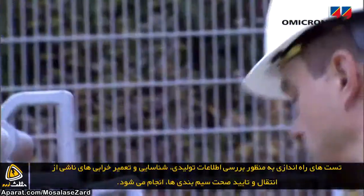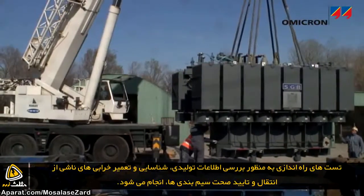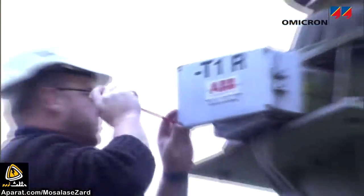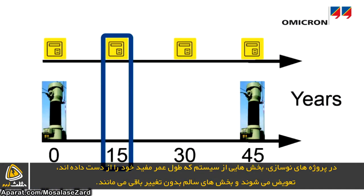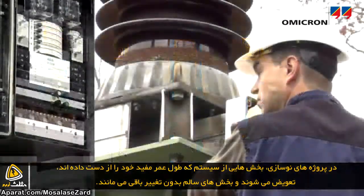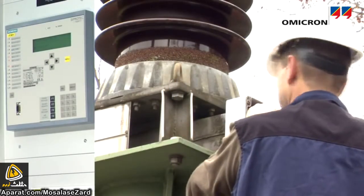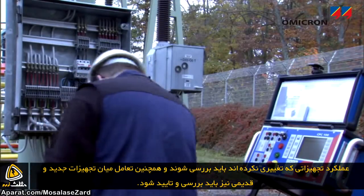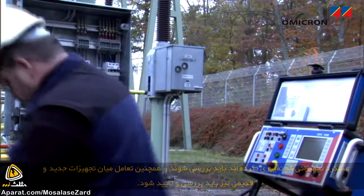Commissioning tests are performed to verify manufacturing data, identify and fix possible transportation damages, and confirm correct wiring. In refurbishment projects, the parts of the system with a shorter lifespan are renewed, while other components remain in service. The performance of the remaining apparatus has to be verified, and the proper interaction of old and new components needs to be confirmed.